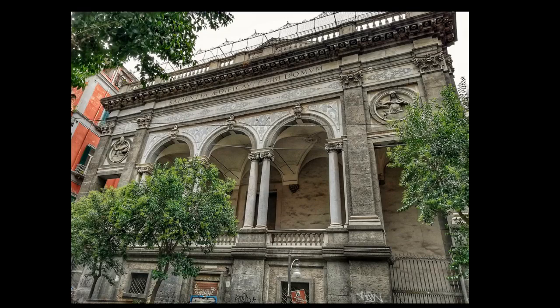So this big element here is another proportion system, has a lower diameter here, but the pilasters usually don't become slimmer to the top, they're just usually vertical. And this one has an entasis, as I explained before, so the columns become slimmer, but the pilaster not. And they have a capital here, and here you see the big entablature that has to fit the proportion of these Corinthian pilasters.